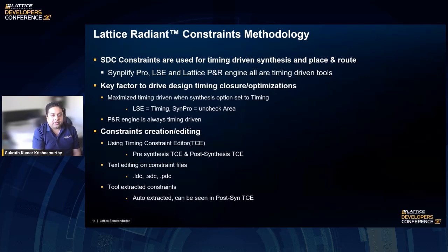In Lattice Radiant, we use SDC constraints, and these SDC constraints are used for timing-driven synthesis and place and route. In Lattice, Synplify Pro and LSE, which is the Lattice Synthesis Engine, are both timing driven. In the backend flow, our place and route engine is also timing driven.